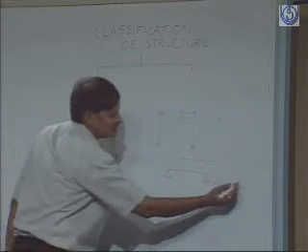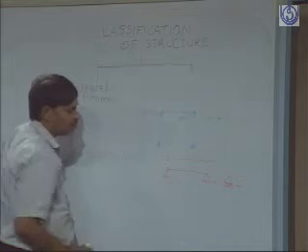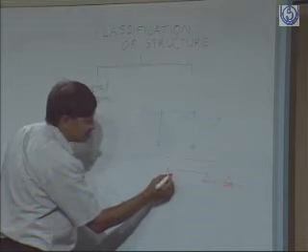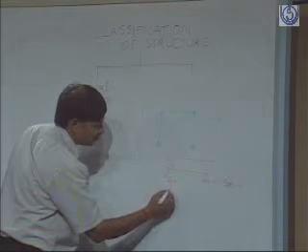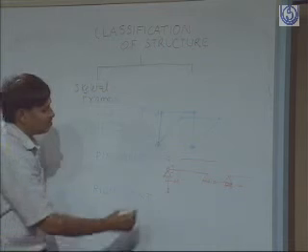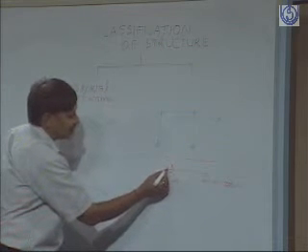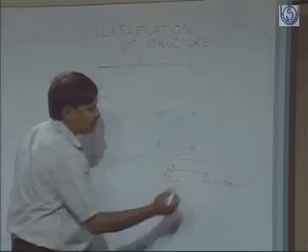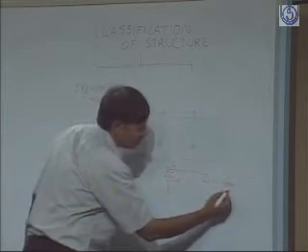So it can also move in this direction, whereas in this type of notation, this is a fixed end, but it can rotate in this direction. These two movements have been restrained, but this movement has not been restrained, as here it is a pin joint, it can rotate. Similar is the case for this joint, but here it can move in this direction.